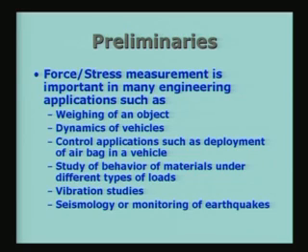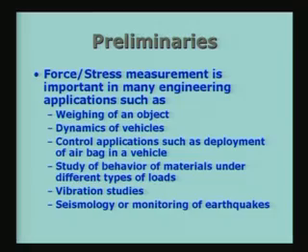For example, you may have a beam which is subject to bending, you may have a ring element which is subject to compression or expansion, or for example a pipe carrying a high pressure fluid inside, it will of course subject the wall of the pipe to stresses, and these stresses we need to measure, or we need to find out what these stresses are, find out whether the safety is taken care of by seeing that the stresses are less than the allowable stresses for the material of the pipe and so on.